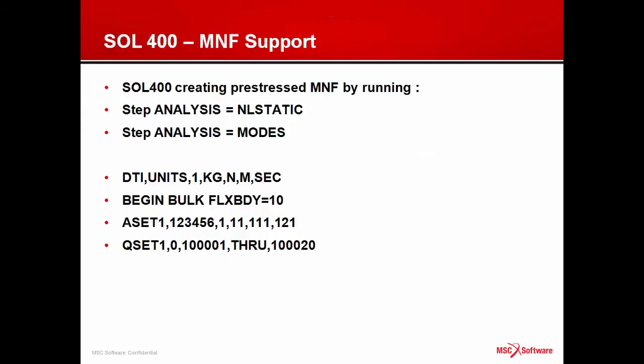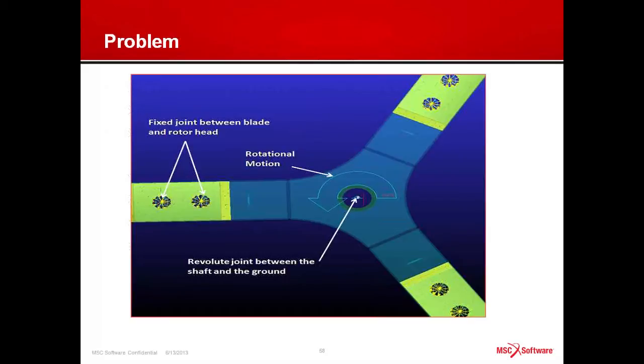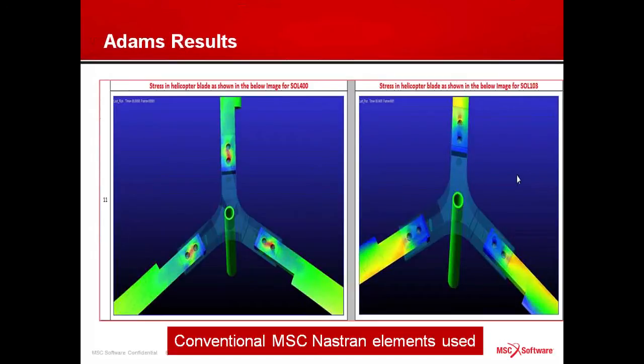Another example, which is being shown here, is a helicopter blade. If you think about a blade as we spin it, effectively the blades go into tension, the stress increases, the so-called initial stress increases, therefore the modal frequencies of the system increase as well.